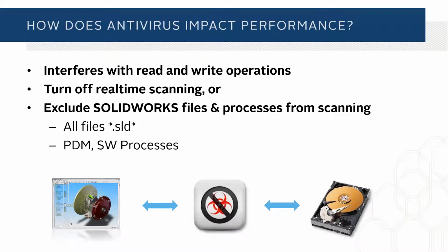Now, am I guaranteeing that no one is ever going to come up with a way to put a virus inside a SolidWorks file and have it execute somehow when it's opened? I can't guarantee that. I'm just saying the likelihood is very, very low, and you can really enhance your performance in SolidWorks file open and save if you exclude the actual SolidWorks files from the real-time scanning of your antivirus software.